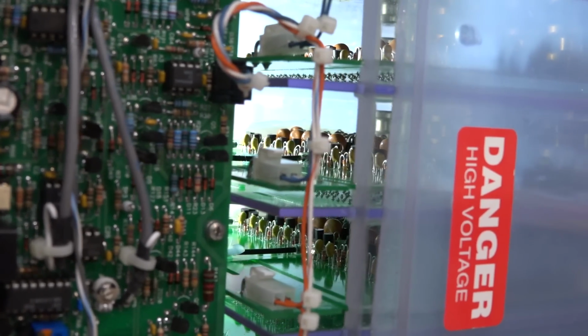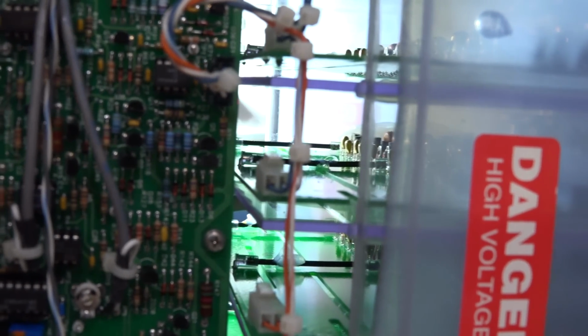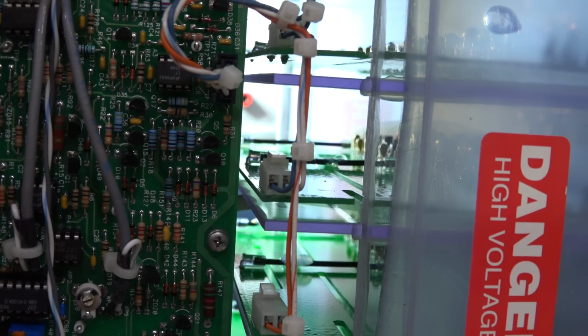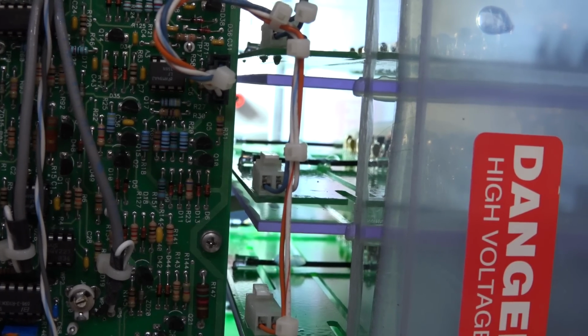So if I move the camera over, you can see the transmitter side. Look at that. It's just some homemade light pipe that they've put together. And look at these big cuts in the PCB to isolate everything. Because remember, that stage over there is tens of thousands of volts above and below ground. So you really have to be far away from each other to not produce any arcing.